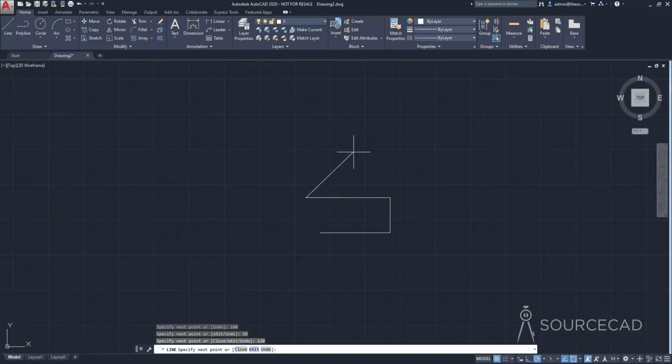And you can even align it in any direction if you want. So I'm going to align it here. I'll type 60, enter, and so on. So you can keep on making your lines by entering the proper distances, and it will just make your line that way. Also in this case, if you want to add angle values, then that also you can do pretty easily. So in this case, let's just make another line of length 100. So I'm going to go to 100 and enter.